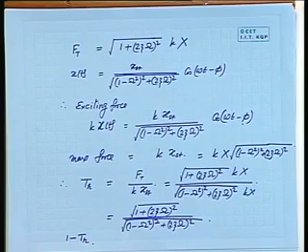Okay. So, now if you are asked to design a particular mount, normally what people say is that you design a mount which will isolate, say, 80%. It will have an isolation of 80%. That means 1 minus TR is equal to 0.8 and TR is equal to 0.2. So, this factor should be equal to 0.2.